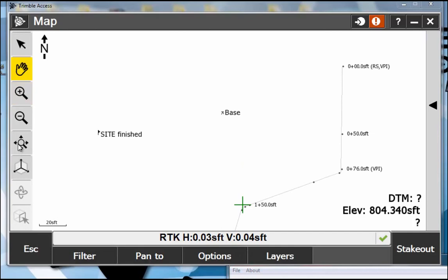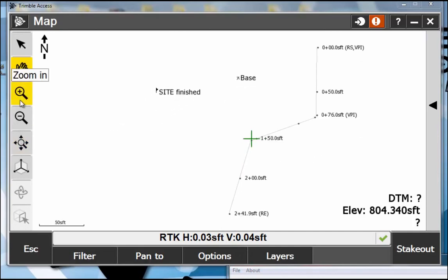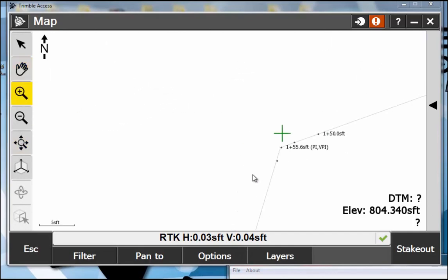All right, so here we have our storm, our pipe run. And notice here we have a few different things, right? We have the invert in, the center invert, right? And the invert out. Those are those 3 points you defined. But we don't have our center of structure on here. So I can stake this out easily, just station and offset like I'm used to. All those invert in, center invert, and invert out, those are all defined positions on my alignment that I can navigate to and stake.